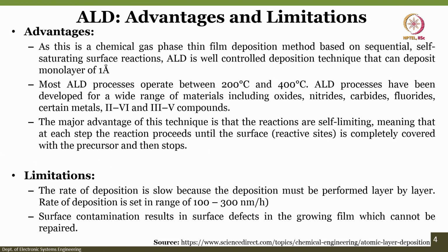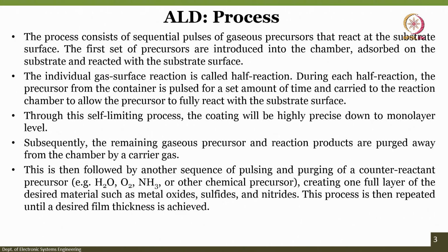But the major advantage of this technique is that the reactions are self limiting, meaning that at each step the reaction proceeds until the surface, at the reactive site, is completely covered with the precursors and then stops, and then we flush and then we introduce the other precursor. Like I said, these are the half reaction steps, or half reaction gas surface reaction, which is called half reaction cycle, right.